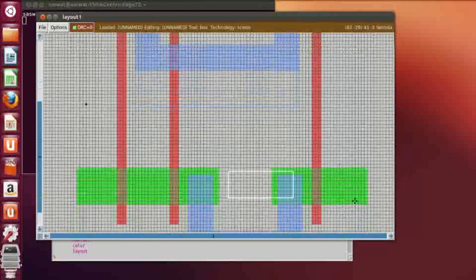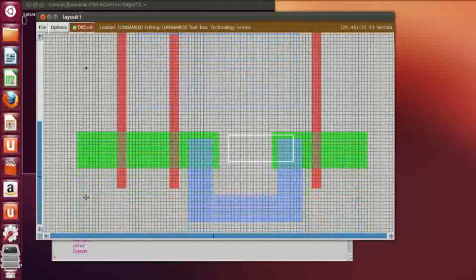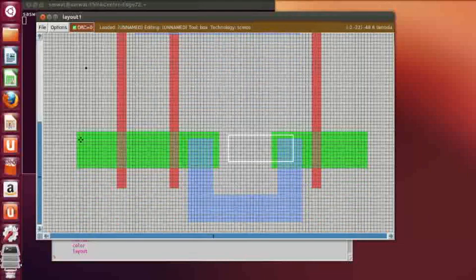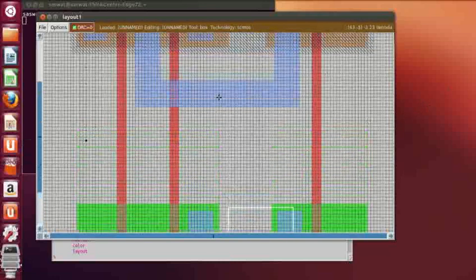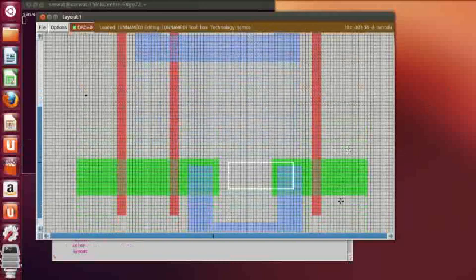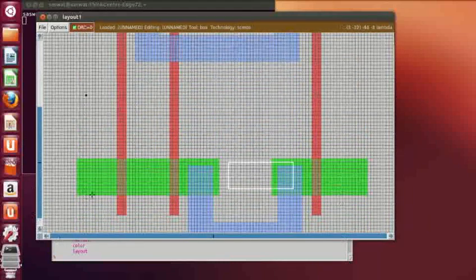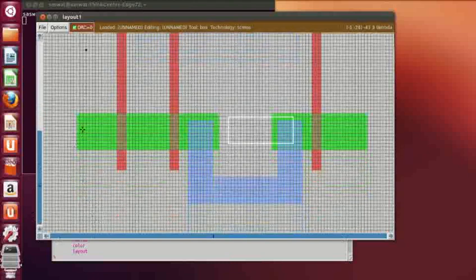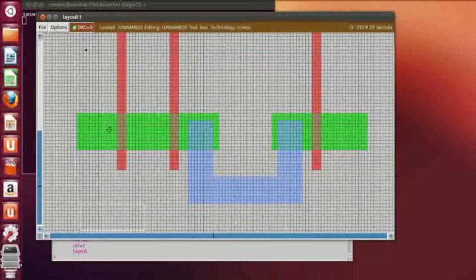So from where will we obtain the output? We will obtain the output from the common drain point of the third PMOS, third NMOS, and the first NMOS, as we have seen from the schematic itself. So at first we'll short these two.